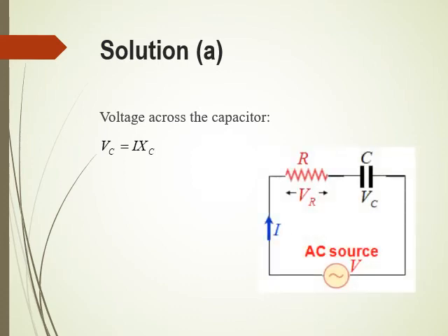So this is the circuit that we have right now, and if you look at the diagram, they are all connected in series. So if the current flowing through the lamp is 0.45 ampere, it means the current for the capacitor is also 0.45 ampere. Let's substitute the values into the equation and you will get Vc equals 0.8 volt.